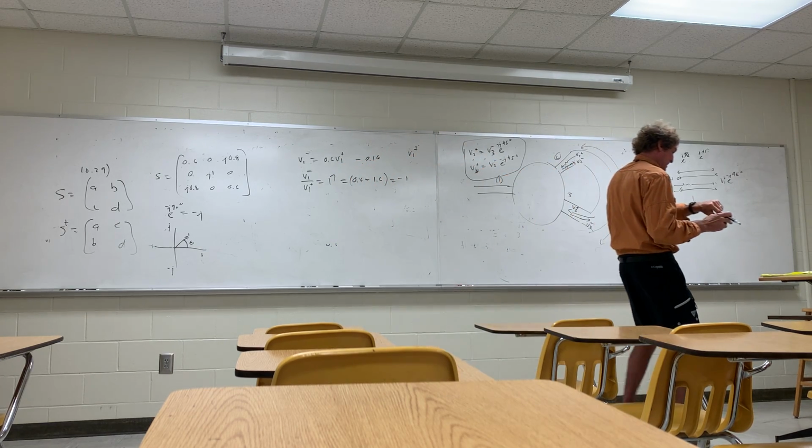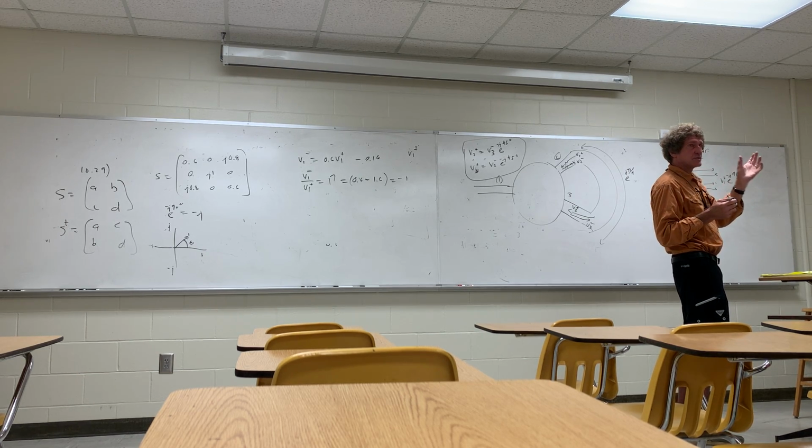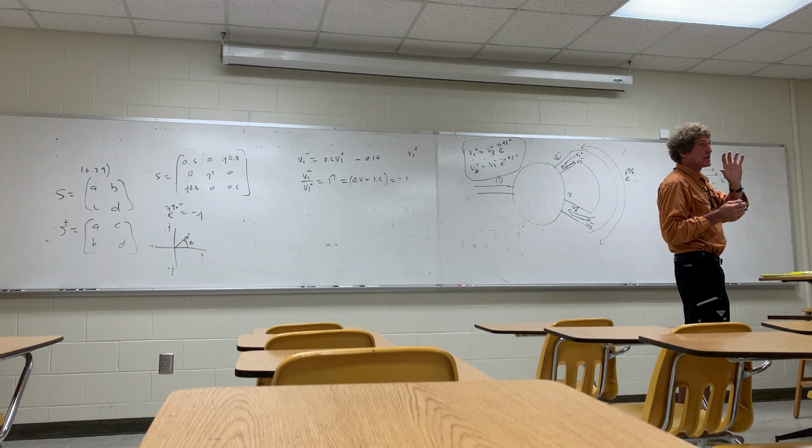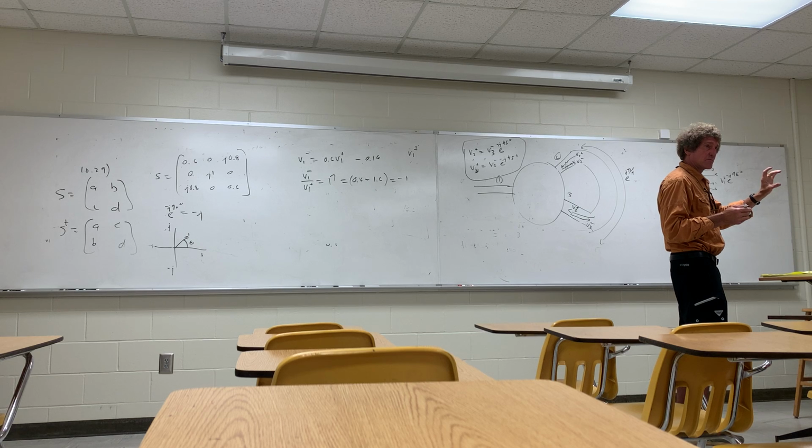That's a pretty good problem. Do you have another question? The other S parameter ones, where they have either capacitors or resistor networks inserted, that's just finding the transmission coefficient and reflection coefficient at each port, and then using voltage division to get the final output for S21 or S12 parameters.